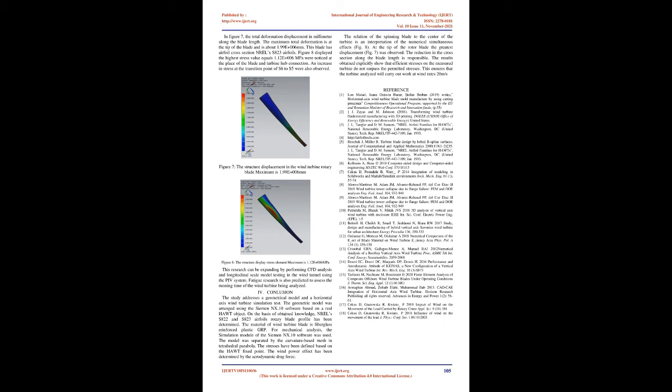It was assumed that the blade's coating, shell, was made of fiberglass. Cyclic symmetry fixture was set as the boundary condition, which allows simplification of the simulation model by analyzing only one rotary blade. The generated mesh of the finite element simulation was a curvature-based mesh with 323,445 nodes and 175,719 elements in Figure 6. For the purposes of simulation, the following values were adopted: V equals 20 m/s, wind speed, T equals 15,980 kNm, torque, N equals 60 rpm, rotor speed.